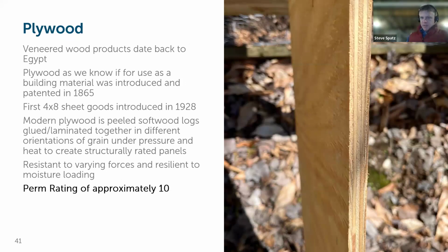So breaking it down specifically into sheathing material options: plywood, CDX as a sheathing material, is wood more in its raw form. It's veneers of raw logs that are glued together. And as a commodity, OSB has dominated the market for sheet goods comparatively to plywood for a long time because of cost. Essentially, it's cheaper to make OSB than it is plywood.